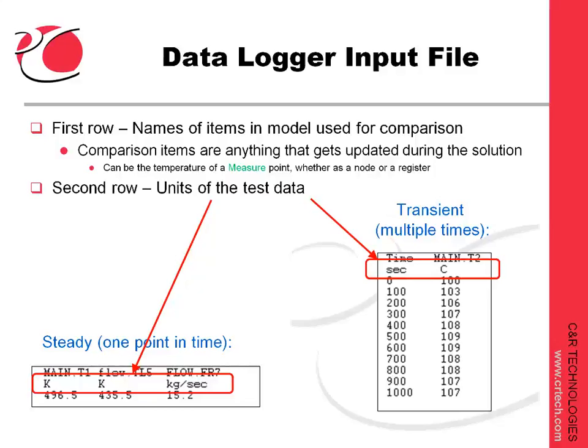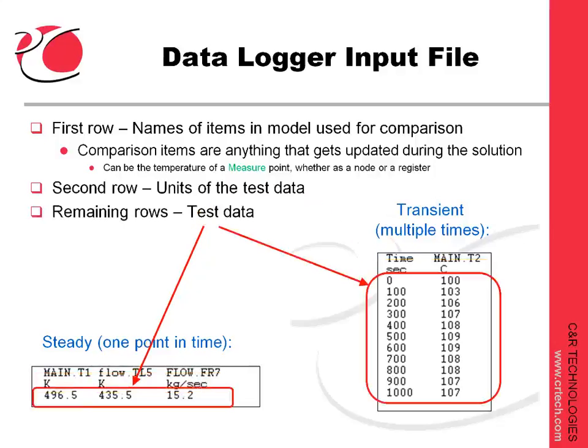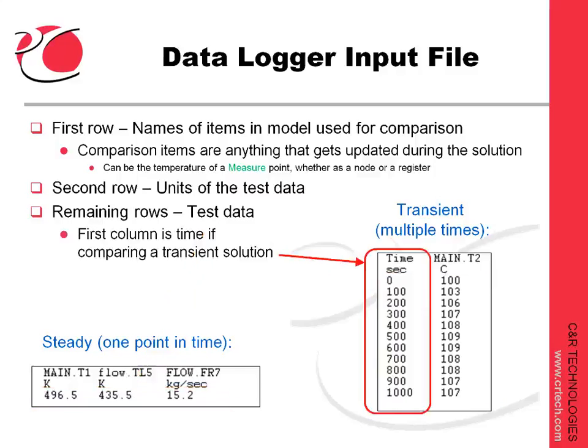The solver will adjust whatever uncertainties you have listed as calibration parameters until the model produces results that best fit the data that you provide in this table. For transient, it will also need to know the problem time for each row, and that's supplied in column 1.